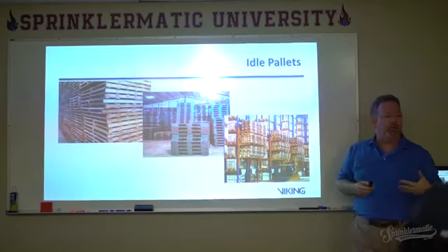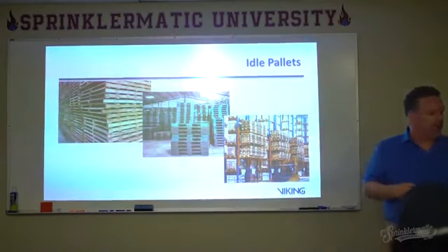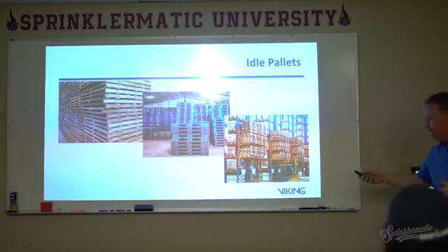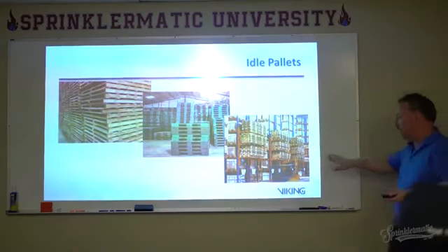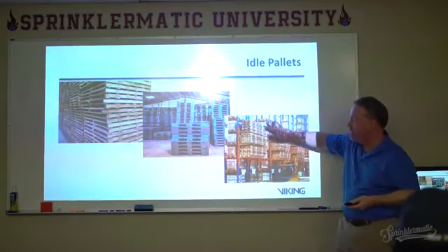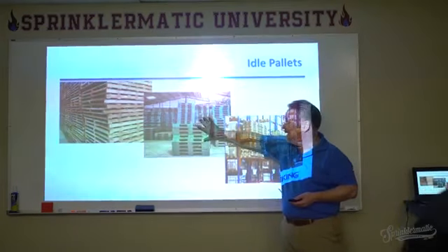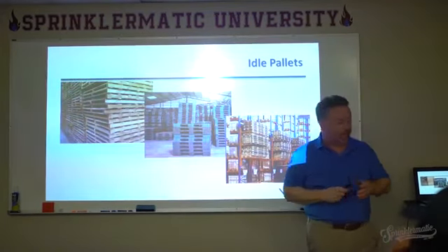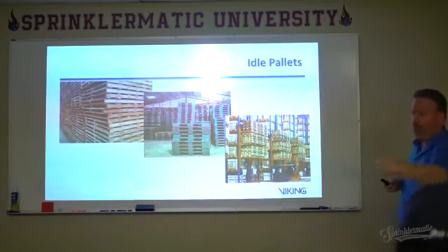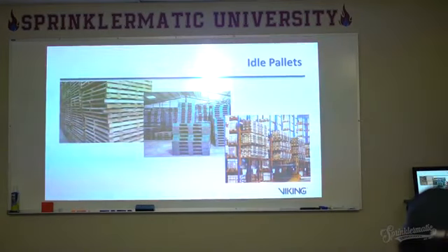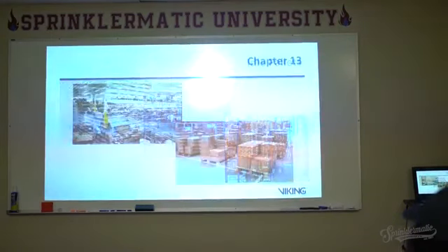I will tell you though that in NFPA 13, if you wind up with idle pallets being stored inside, either attached to the racks or inside a building, here's some plastic pallets over there, or some wood pallets there, Chapter 12 does have specific guidance on protecting inside. And the best thing that they say about protecting inside, as I said before, is get them outside. All right, don't store them inside.